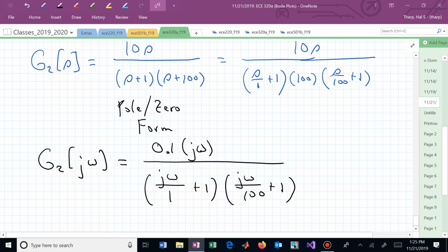So what do we consider small for a generic transfer function? You would look at all of your breaks, all of your poles and zeros, and you go, let me go a decade below the smallest one. And that's going to be my small. You do the same thing for large, and you say, oh, let me find all my poles and zeros, let me go to the biggest one, and then I'm going to go a decade beyond that and say, oh, here are my frequencies that I'm considering big or high. Clear on that? What's the phase of this transfer function for small frequencies?